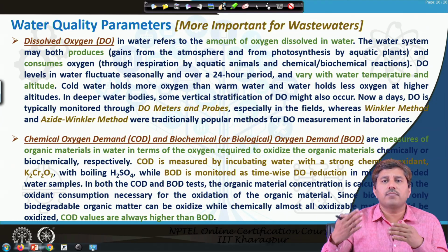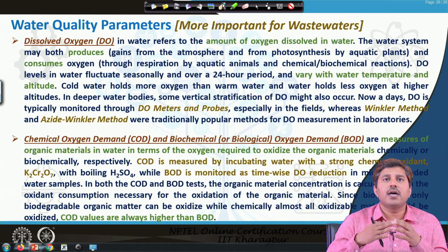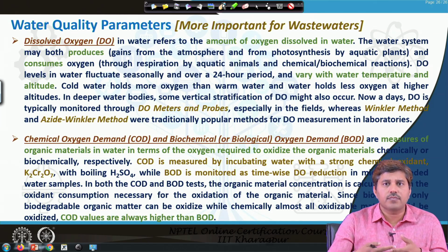So, if you measure the dissolved oxygen in a water body in the afternoon, you are likely to get more DO as opposed to measuring the same water body at night. Also, it varies with the water temperature and altitude. Cold water holds more oxygen than warm water. As the temperature increases, the oxygen is not retained in the water and escapes to the atmosphere.